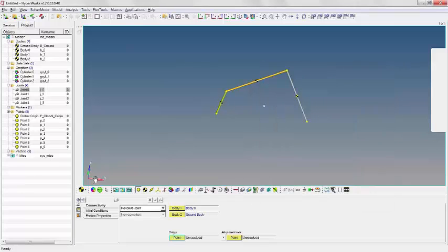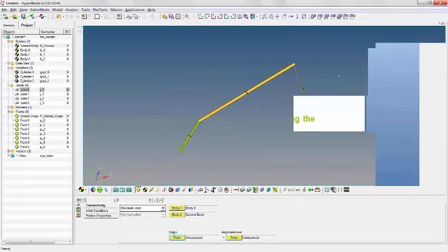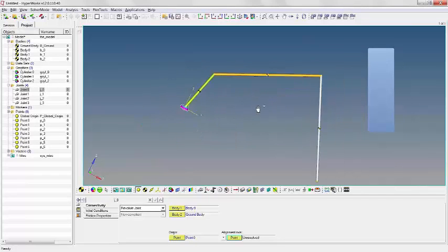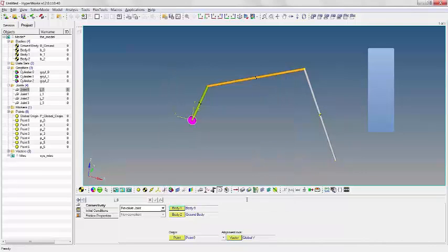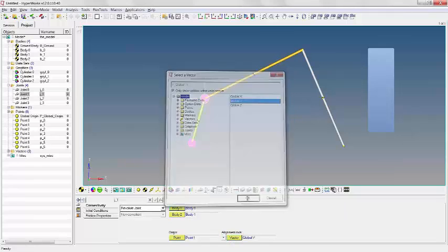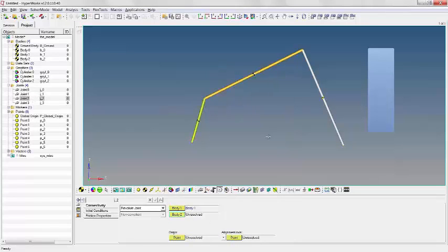This is the point of origin for the revolute joint, and I'll align this around the y-axis. Similarly, I'll do the same for the remaining 3 joints. For the second joint, I've used these 2 bodies, and this is the point where my joint goes. The last one connects the ground body and the last body too over here.